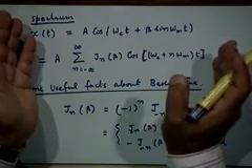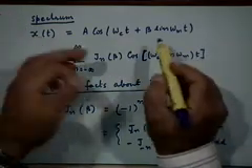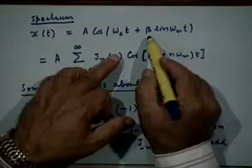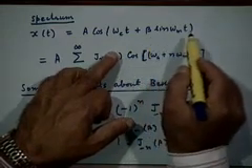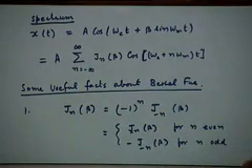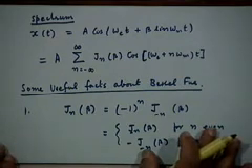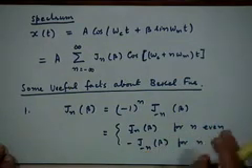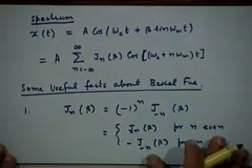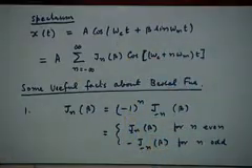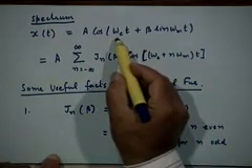The frequency deviation expression becomes beta times omega m into cosine omega mt. Maximum value of cosine omega mt is 1, so the maximum value of the frequency deviation would be beta times omega m. So beta times Fm is nothing but the maximum or the peak value of the frequency deviation that this signal will exhibit. You understand the definition of frequency deviation, with respect to the center frequency.